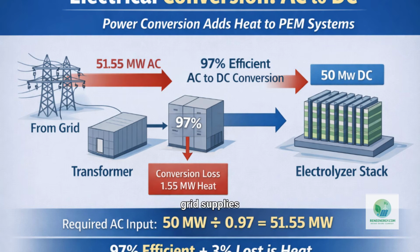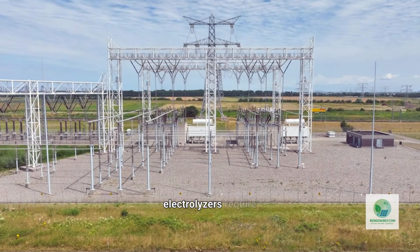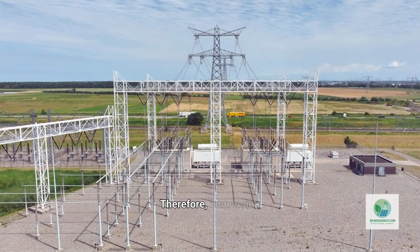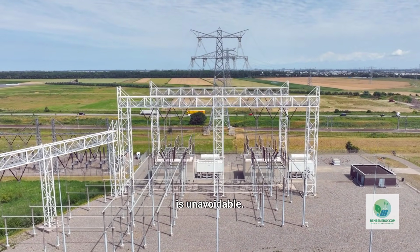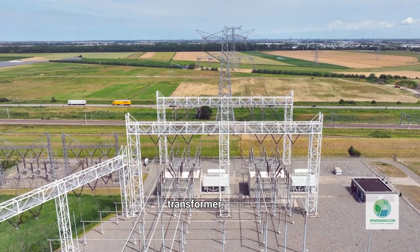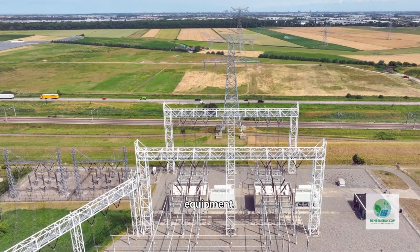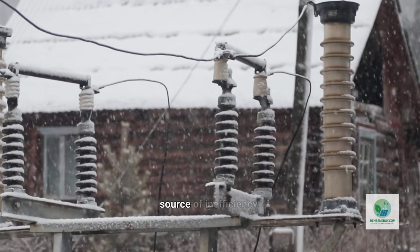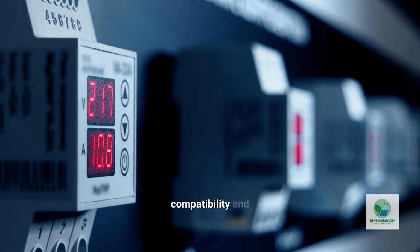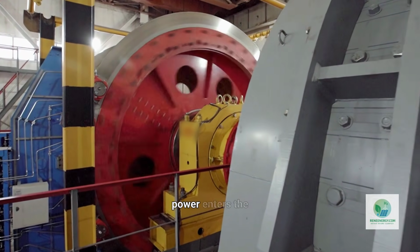The electrical grid supplies alternating current. However, PEM electrolyzers require direct current. Therefore, a conversion is unavoidable. Power first enters the transformer, which adjusts voltage to appropriate levels for downstream equipment. The transformer is not the primary source of inefficiency. It ensures voltage compatibility and safe operation. After the transformer, power enters the rectifier.